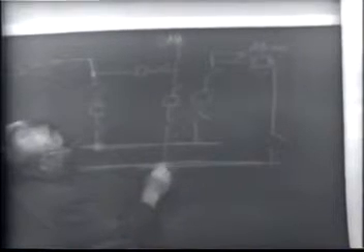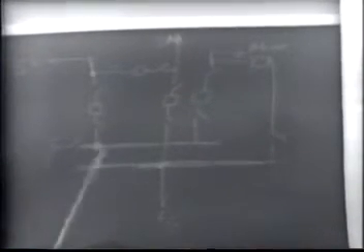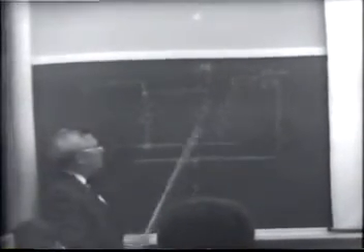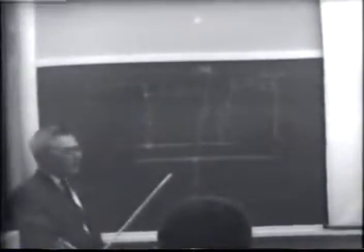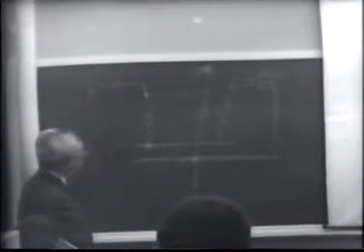We have a bus here. We have a bus here. We have a connection, this loop here, electrical connection here. And there is one bay of a breaker and a half scheme. By adding another breaker over here, we can have another breaker and a half bay.